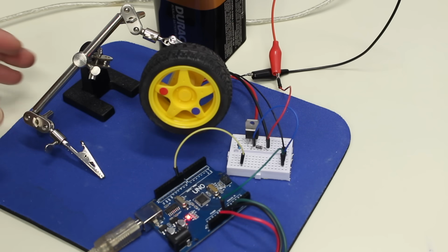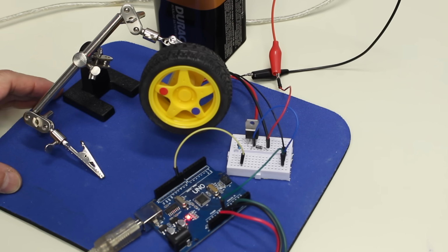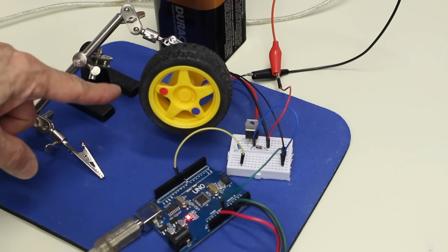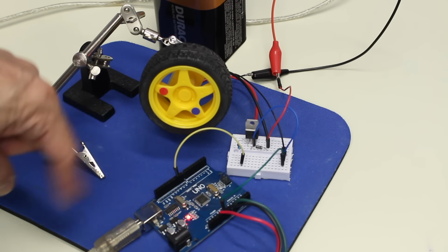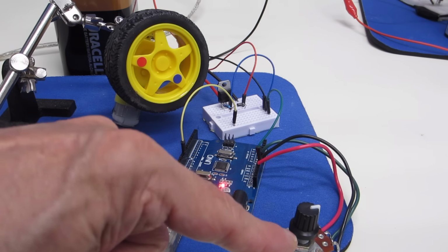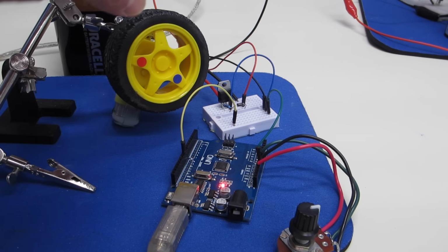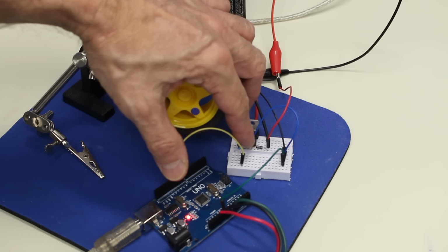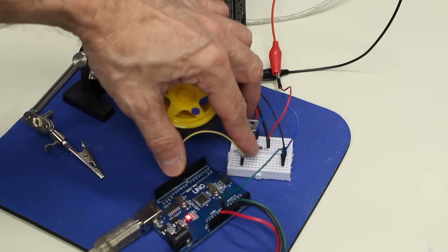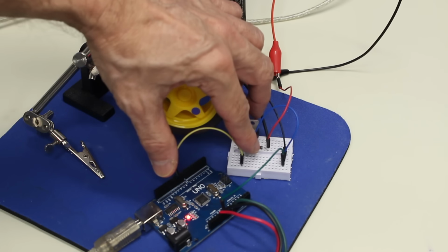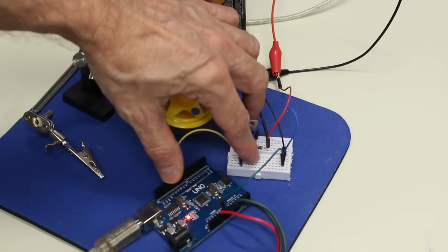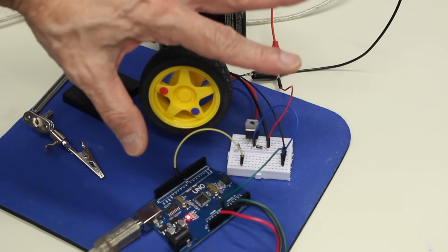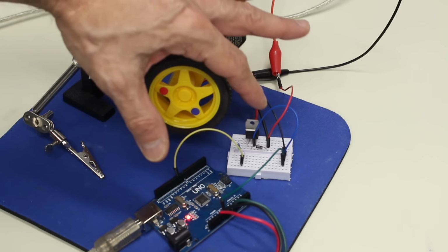And so here's our motor control demo ready to go. Now, of course, I've got my battery back over here powering the motor, and I've got a small DC gear motor attached to this wheel, and we're going to spin it around. Here's my potentiometer, my Arduino, of course, and then back here, my TIP120, and here is my diode, my 1N4004 rectifier diode. Now, it's very important, again, to make certain that the line, which is the cathode, is connected to the positive side.